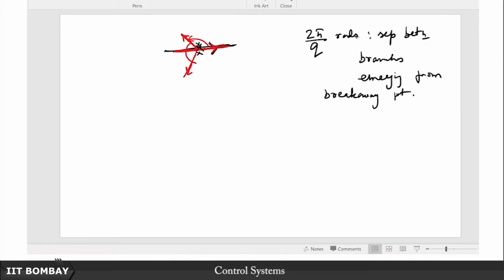So this is slightly different from the effect of pole zero that we studied earlier. Remember, earlier we were just talking about this transfer function, expanding it into its partial fractions and looking at the weights on these different factors that we had isolated. So we looked at these residues, and we saw that if a certain pole is more than 5 times away from the dominant poles, then we can jolly well ignore its effect. That was the way we were looking at it earlier. But now this deduction that we made in the last lecture didn't have anything to do with the standalone system, it was about a closed loop configuration.